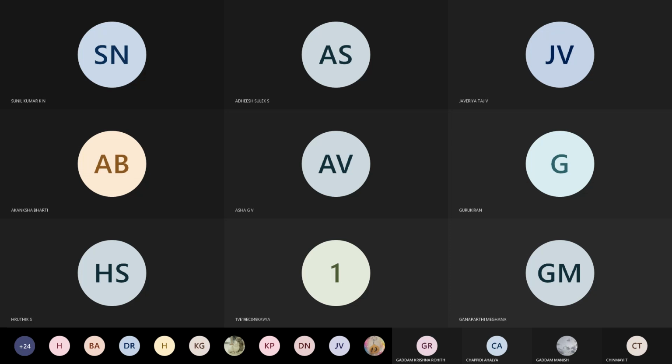So with respect to VA alone, V1 will be equal to VA into R by 2 divided by R plus R by 2. This is the voltage drop appearing across the node V1.